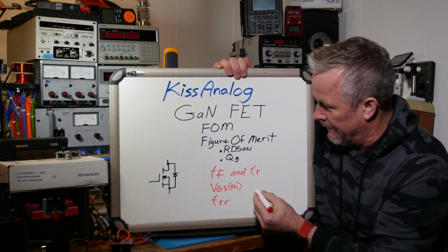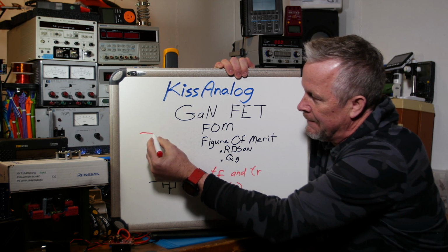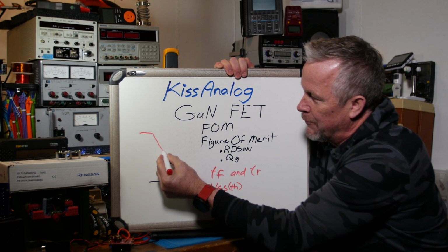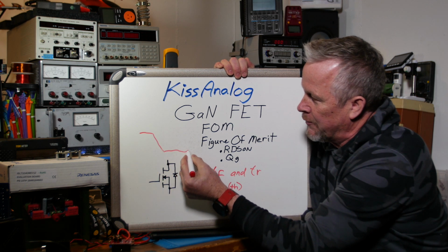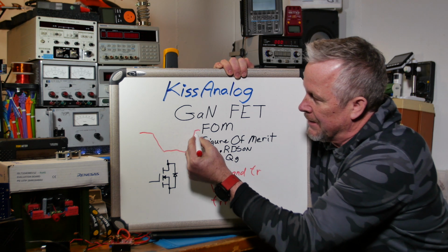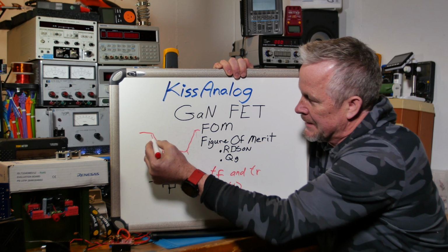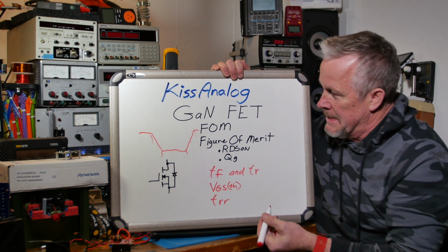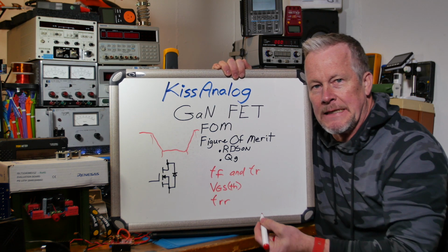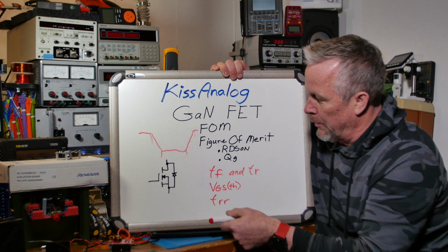If the FET is on and you turn it off, it has a fall time. I'm exaggerating this. Then it's on for a while, and then you turn it on and it comes up. So this fall time and rise time doesn't happen instantly like we'd like it to. So those two things are important factors.